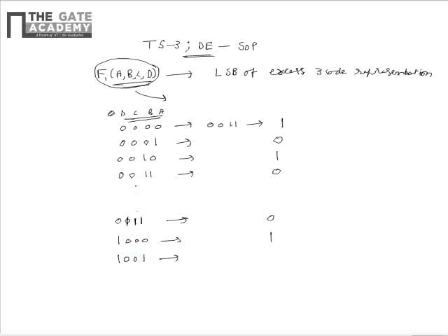1001 maps to 0, and from 1010 on all are don't care options because 1010 maps to 1011, which is not a valid excess-3 code because 1010 doesn't correspond to any BCD value. From this data we see that the map representing the above can be drawn as shown.